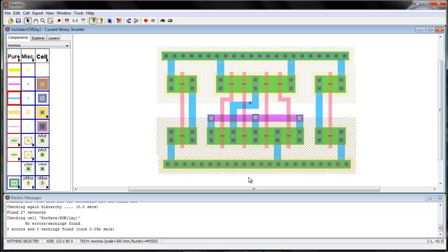Till here we are done, but just a piece of advice: like how I check for DRC errors after every 2 or 3 connections that I make, you also check for DRC errors every now and then, because if you just accumulate them, they will go on to 20, 25 and I don't know what all number. But then just try to minimize the errors at every step.